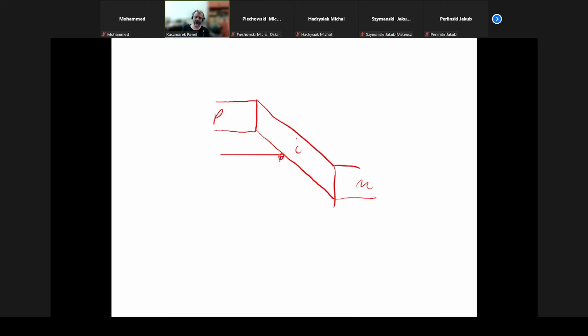Yeah, so we are creating an electron-hole pair. They are, of course, separated by this electrical field, but the electrical field is so high, close to the breakdown voltage for such a structure, that the energy of this electron is increasing. It is accelerated by this electrical field, and this energy can be higher than the ionization energy for this semiconductor.